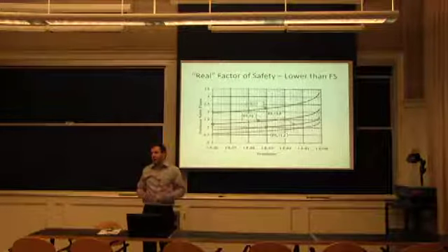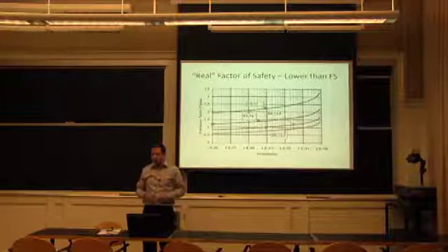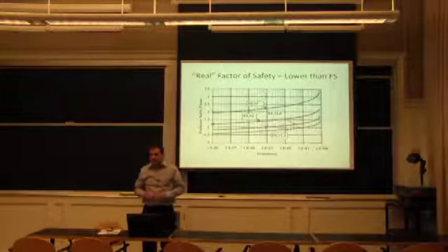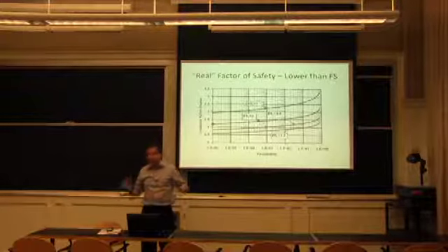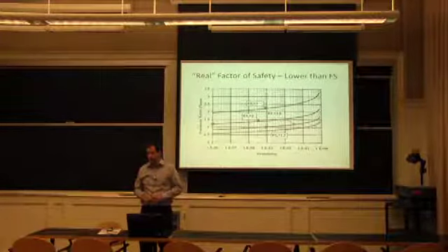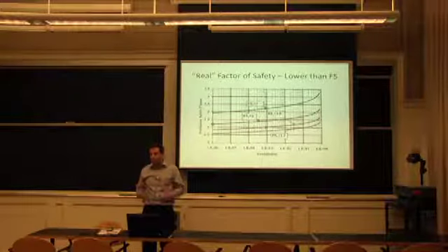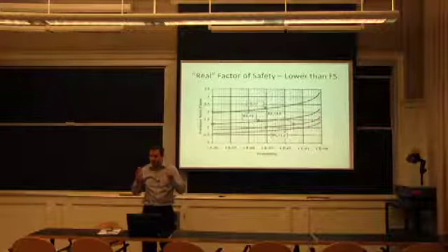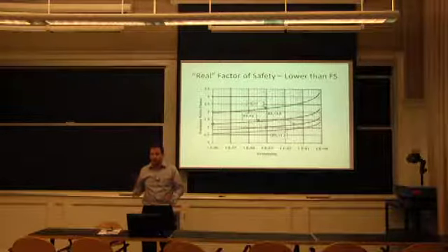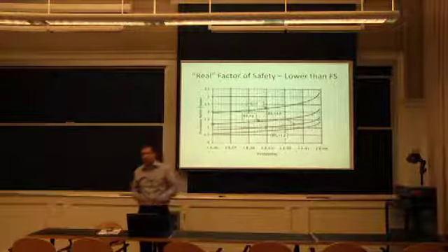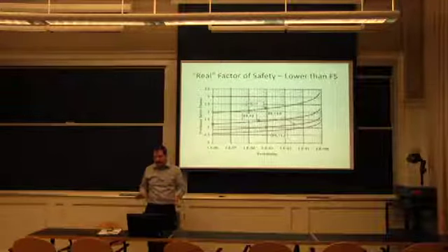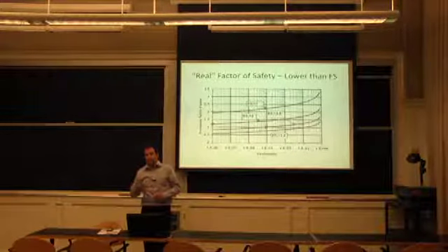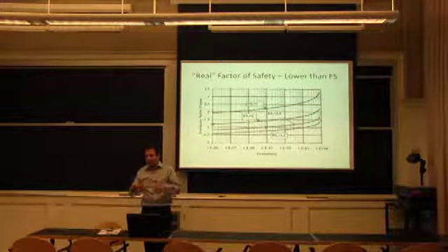That's really what I want you to keep in mind, that when we do a bridge, it's not because it started with a safety factor of 2 that you can add 20% of construction load at any point in time on it. You don't know what the actual factor of safety is for this structure as it was built a while ago, went through service, corrosion, everything you name it, the added lanes. Anything that can happen will happen sometimes. And it's all taking up that starting pie.